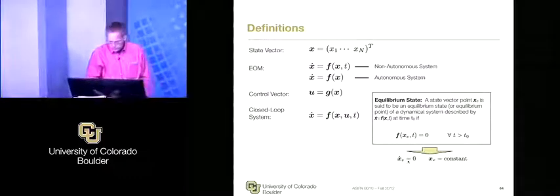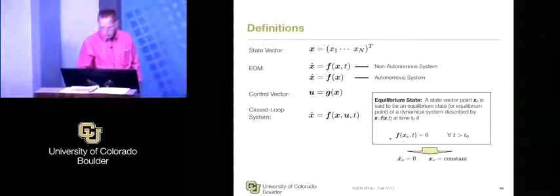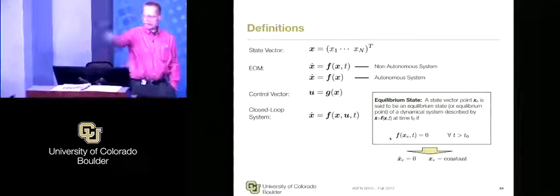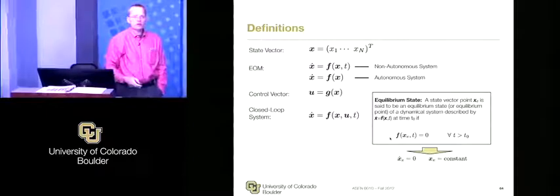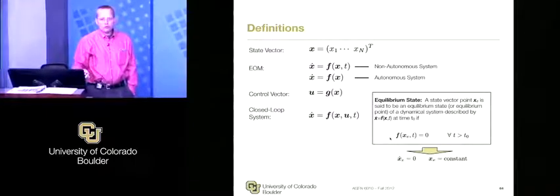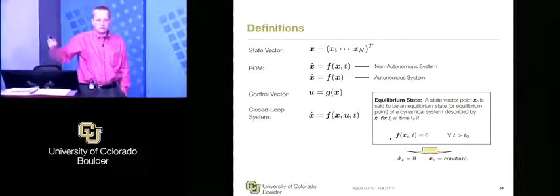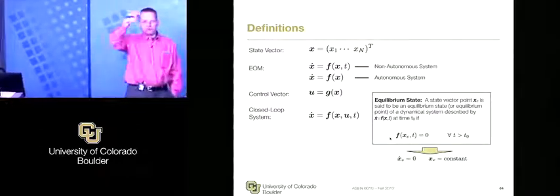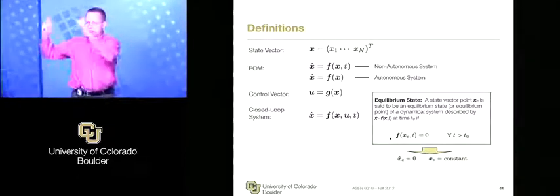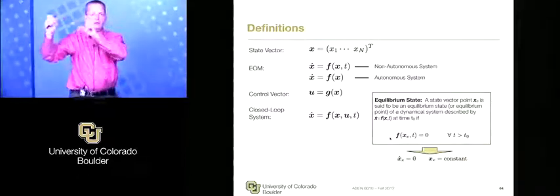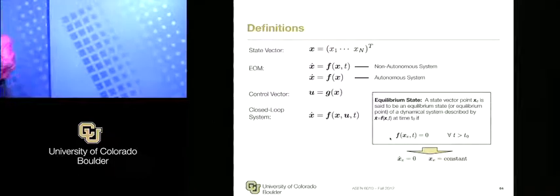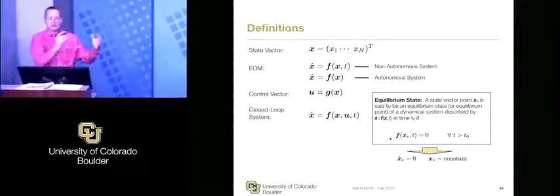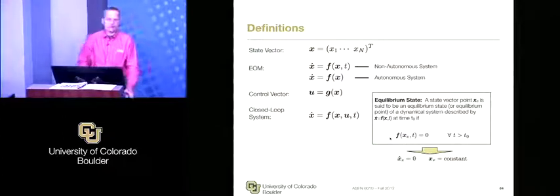From a feedback control perspective, we often get to choose. Maybe having the satellite do this motion isn't a natural thing. So now I get to choose a control which makes it converge to this. Essentially, you're introducing an artificial man-made equilibria, right? And you're forcing with these reactions and how they're firing that this craft will actually stabilize onto that motion. Just like this pen is stabilizing on a table. I don't like the natural dynamics, so we get to modify it. That's what feedback control does. So quick definitions. Let's go through here.